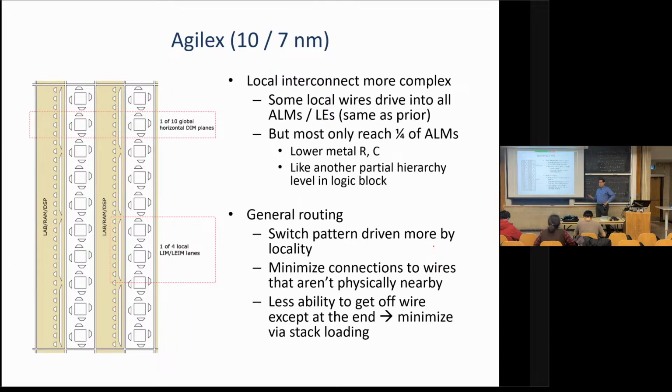So metal resistance is getting bigger, even for relatively short wires, because inside the logic block, we really can't use those fat wires, right? We're reserving those to go long distances. So we've got to connect up what's inside the logic block with pretty low-level wire, where we've got a lot of it. And that's becoming resistive, like noticeably resistive, even for fairly short distances, the kind of distances you get in the logic block.